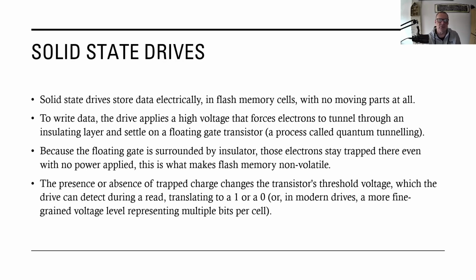Our third technology we use is solid state. And solid state uses electronics rather than magnetics or optics to store data. It stores data in memory cells. There are no moving parts at all. When you want to write data, the drive applies a high voltage that forces electrons to tunnel through an insulating layer, and then they settle inside a floating gate transistor. And that process of pushing the electrons through this insulating layer is called quantum tunneling.